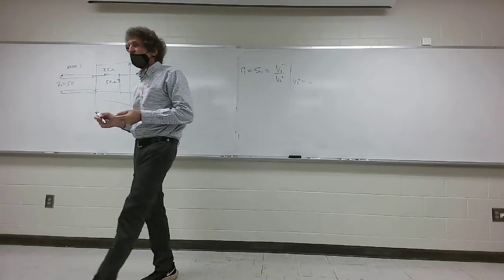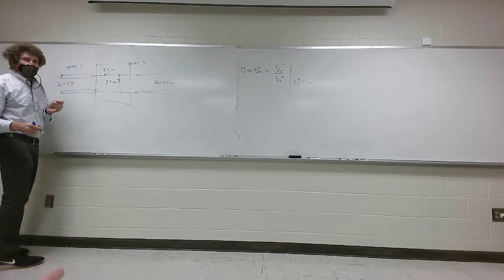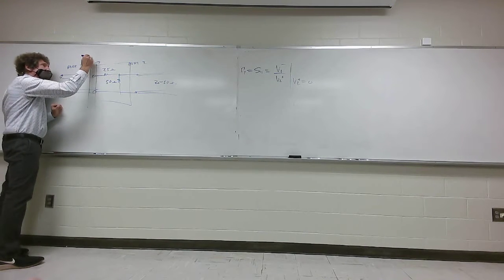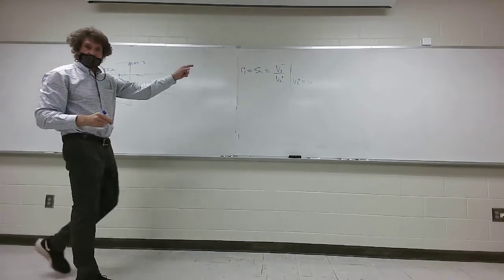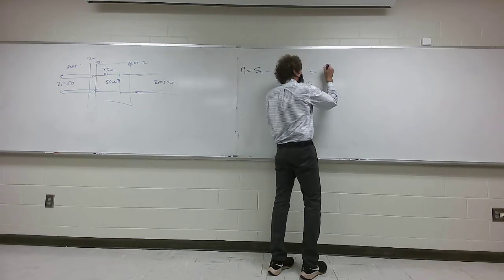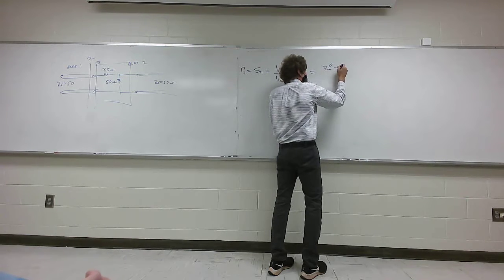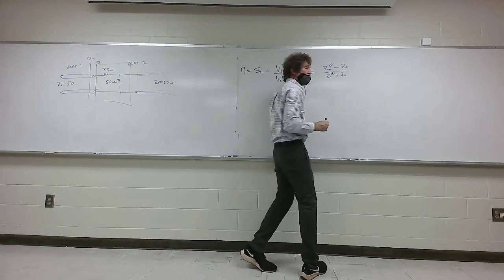Let's talk about that and do it. Now, if you're doing reflection coefficients, what are you always looking for? You're looking for the input impedance, right? Isn't that the key thing? Because reflection coefficients are always what? They're the impedance you're going into, in our case, Zin on port 1, minus Z naught over Zin on port 1 plus Z naught. Do you all agree with that?